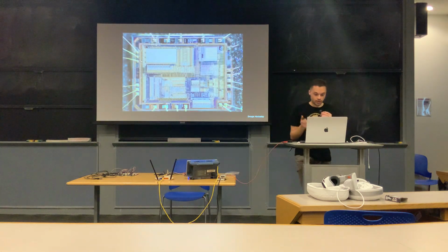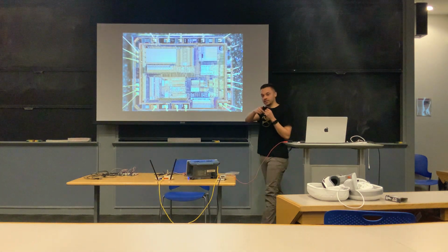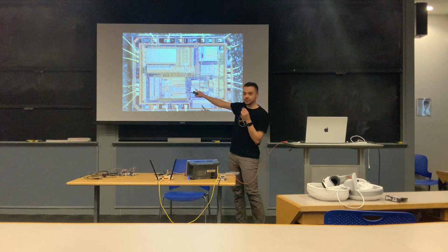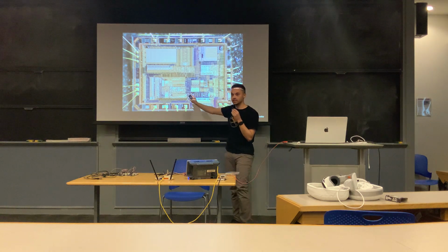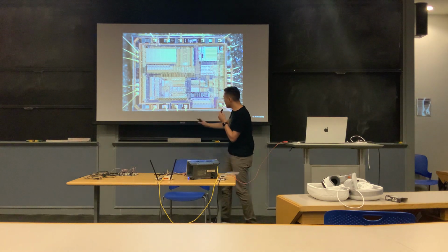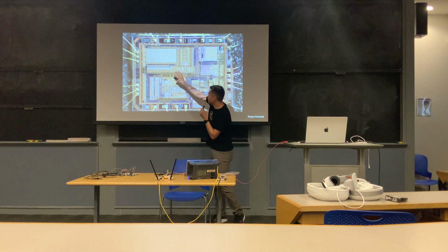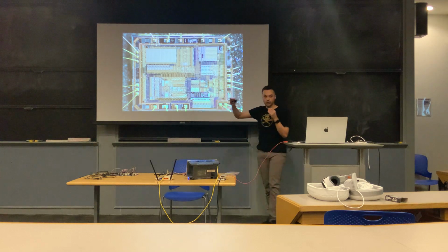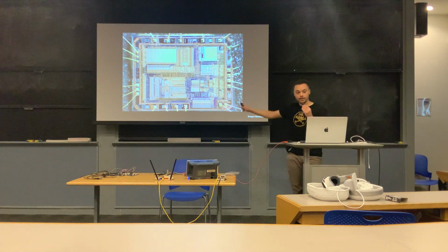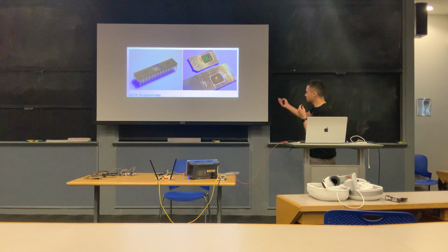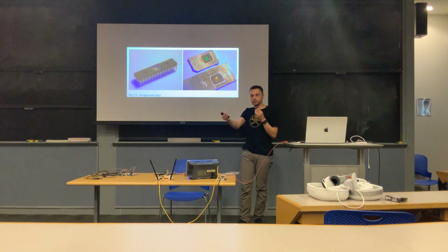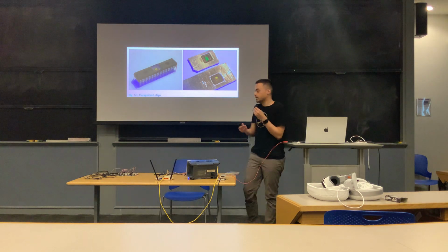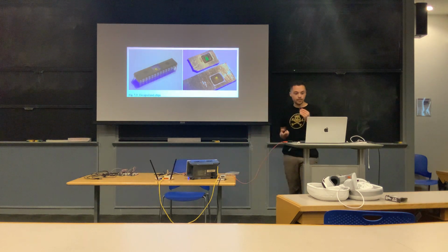Cool. So you just asked what does it look like when you take the cap off a chip? This is the inside of a chip. So in case you've never seen before what's inside of a chip, this is your actual silicon substrate. So you can see we have these wires that are bonded onto the pads, and this is the silicon of the actual chip itself. So if you were to successfully decap a chip, this is what it would look like. So here's some more photos of decapped chips. So you can see we have full exposures of the silicon. You can actually read back, take photos of the silicon, try to reverse engineer it, do things like that.